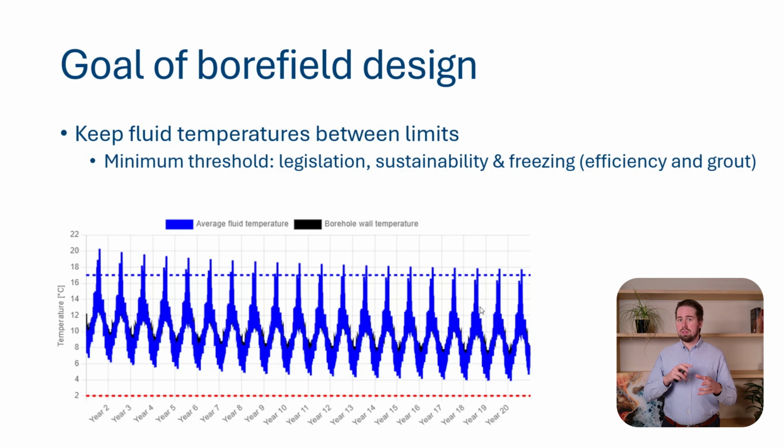But also, depending on the type of grout you're using, having negative temperatures for a longer period can cause this grout to crack because there is moisture in it. And when this moisture freezes, it causes such an internal pressure that the grout may crack and that your borehole actually gets damaged. And if this repeats season after season, in these cracks, groundwater comes, it freezes again, it cracks more open, and you're ending up with a borehole that has a totally cracked grout, and then also the heat conductivity is no longer guaranteed. So that's an important thing. Please stay away from these negative temperatures.